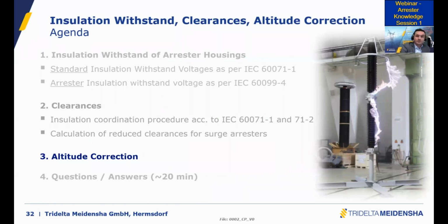Okay, so next topic, altitude correction. You've seen that we have already considered altitude correction for the clearances calculation, or for the insulation withstand calculation for the arrester housing.